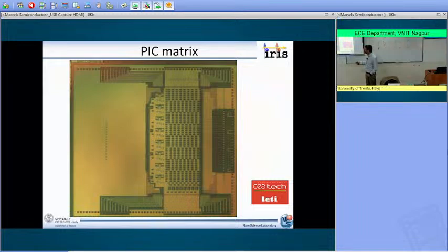before bonding. Here you see the gratings, the different gratings. So you need to have 4 gratings for the direction and 12 gratings for the add drop channels. Then here you see all the different microring, double microring resonator-based switchers. Here you see the demultiplexer, the AWG. Here you see the interleavers. In the output you have again the interleavers.